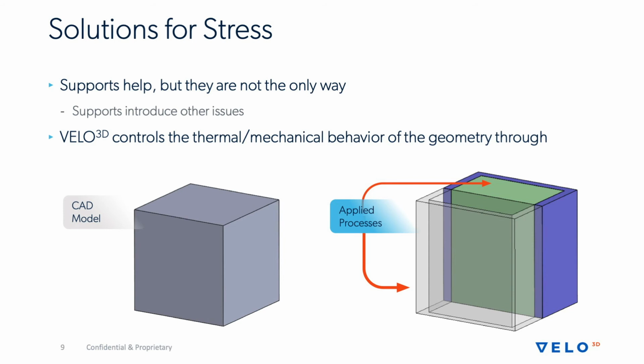What I'm representing here is this green center area, which is something of a bulk fill area. Those laser commands and that process are optimized typically for throughput and density, but not necessarily for surface finish. So it's very common that you'll split out the bulk fill and the skin, or the very outside surface of the part, into a different process. The skin process is typically optimized for surface finish.